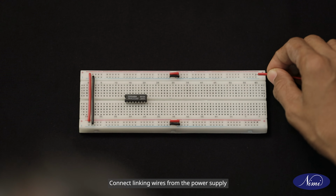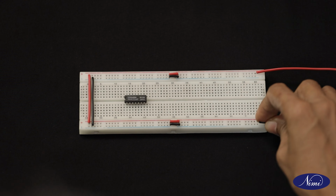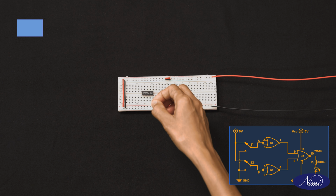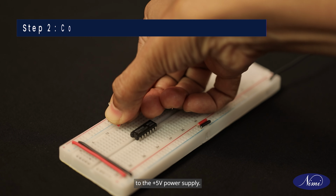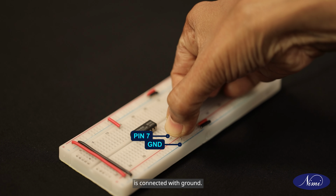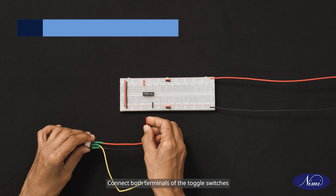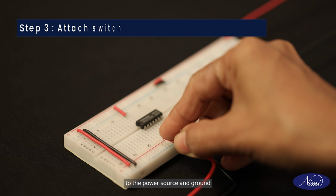Connect linking wires from the power supply to the breadboard. Next, connect 14th pin of the IC to the plus 5 volt power supply. Then make sure pin number 7 is connected with ground. Connect both terminals of the toggle switches to the power source and ground.